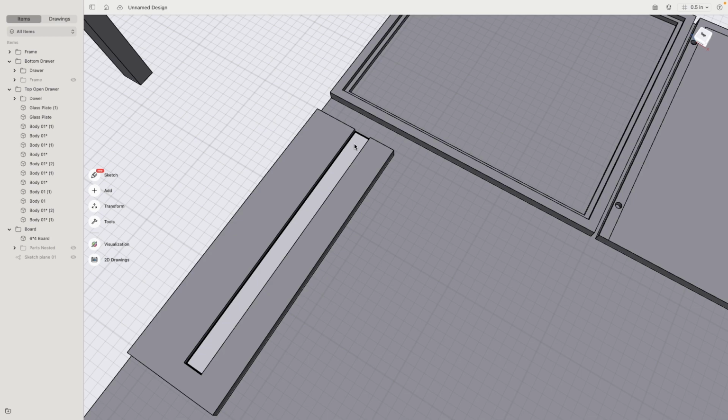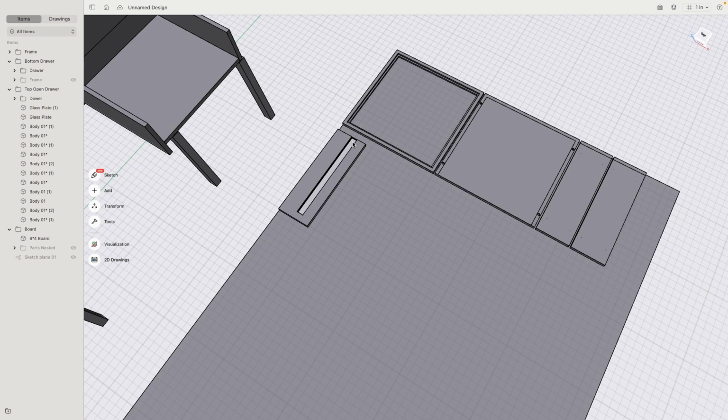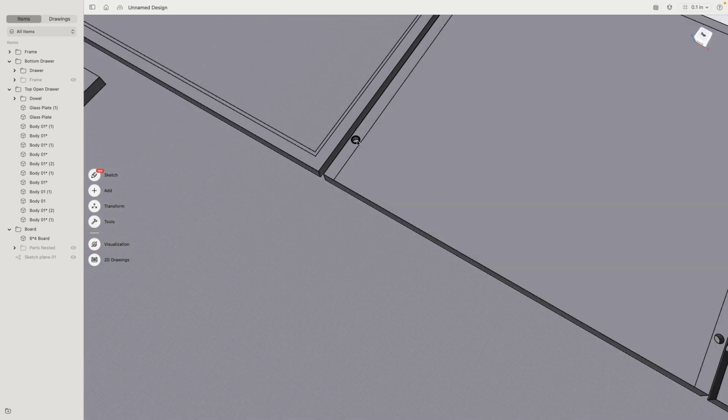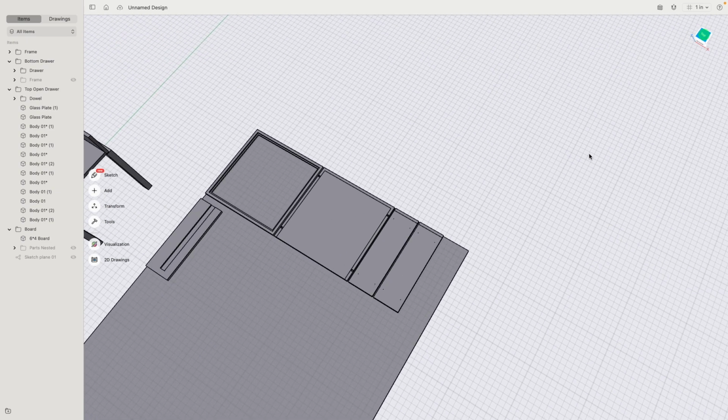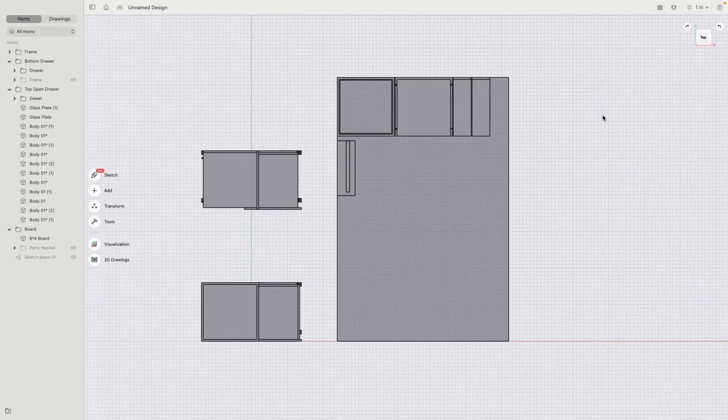Because the thing is now, do I have just a cutting tool that cuts the raw pieces out, or do I actually have a CNC machine that not only cuts the individual parts out, but also does all the details? So for example, these screws will be cut out. I will have here a router bit that will mill the holes for me perfectly, so I don't have to use a drill press. The CNC machine does all that for me automatically. So once all the cutting is done, I have all the finished pieces. I can finish them and put them together.